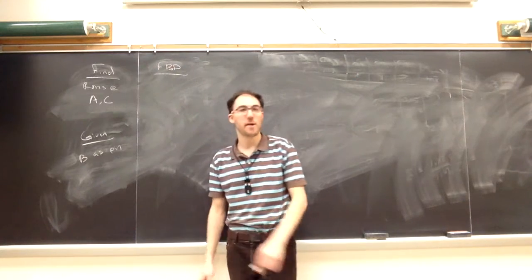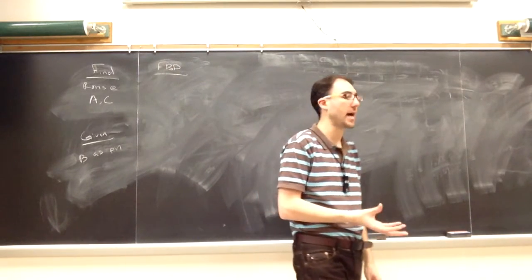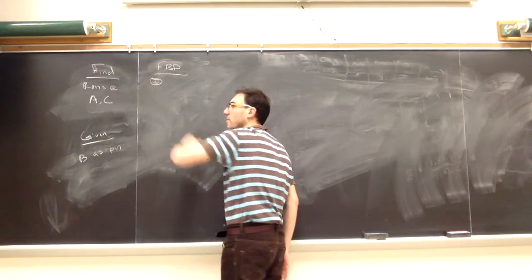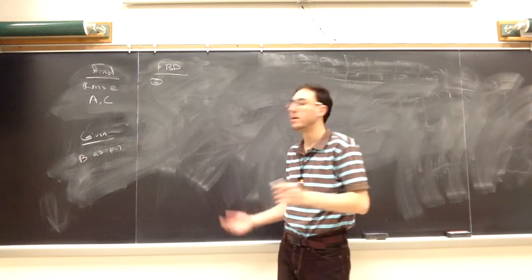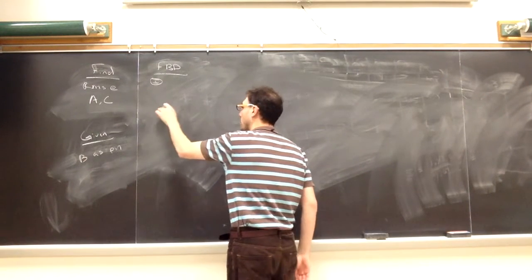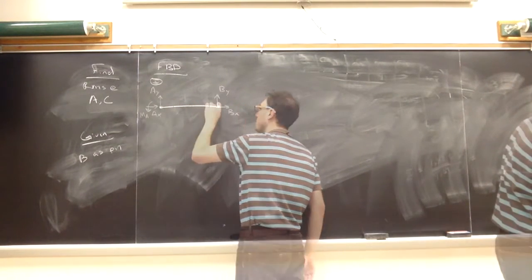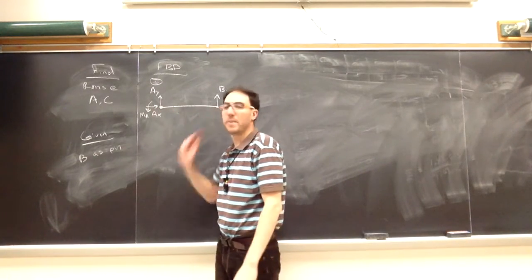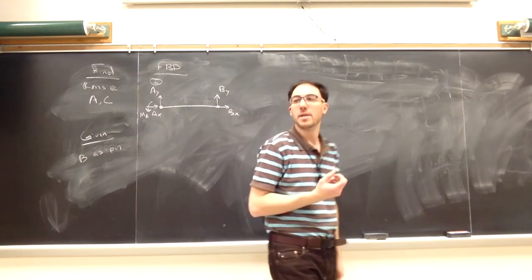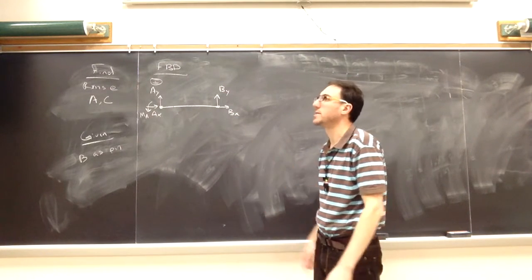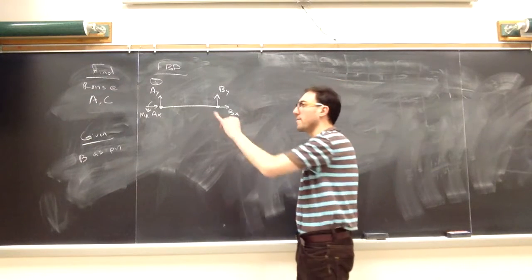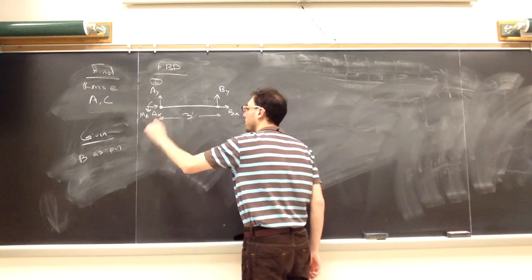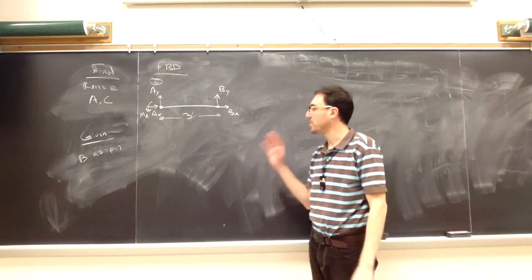We know if it's a frames and machines problem, we'll need at least 2 free body diagrams to solve it. As I've been doing, I'm not going to draw the external picture, although we could. I'm going to jump right to that internal picture. So 3 at A, we have an internal pin support at B that I'll call BY up and BX in this. And we know that from A to B is 3 feet. I have my external supports, my internal supports.